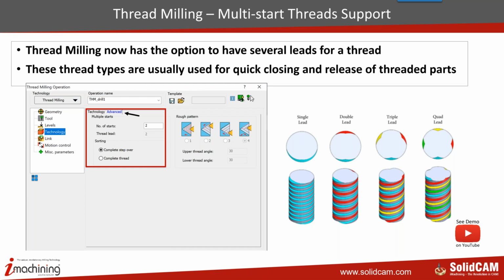You could choose the type of thread you needed, the standard that you needed, how deep you wanted to go, but you had absolutely no control of your lead-ins and lead-outs. You had no way of dealing with multi-starts. And when you did rough cutting, there was very little you could do. You just hold it, step in, and every single time it stepped in at each time.